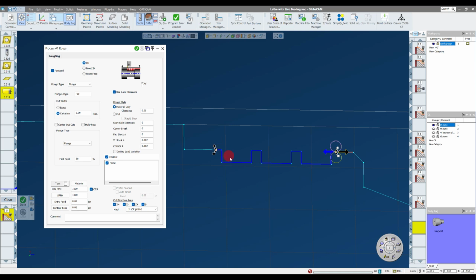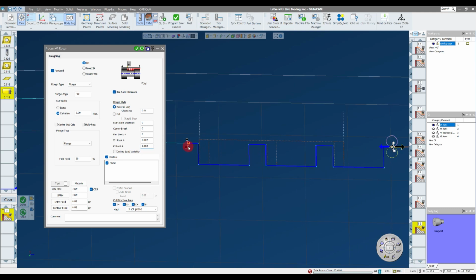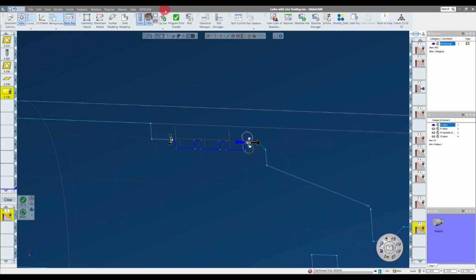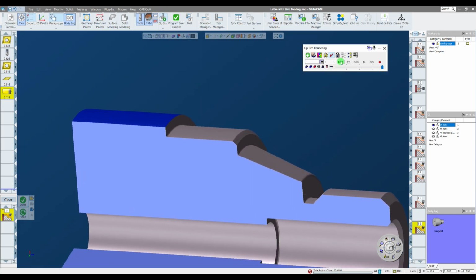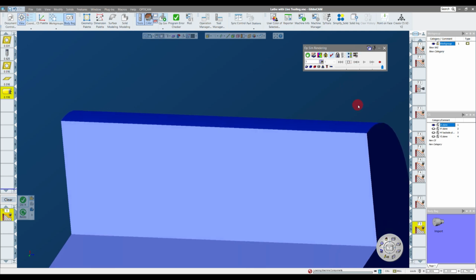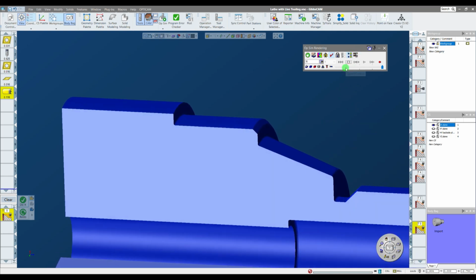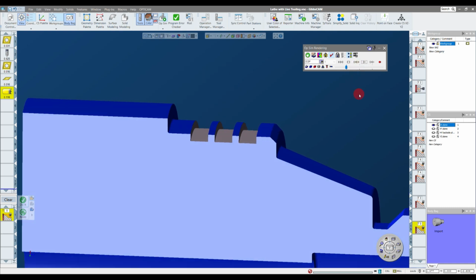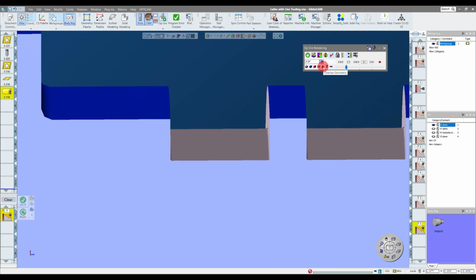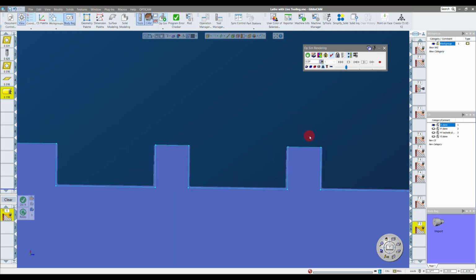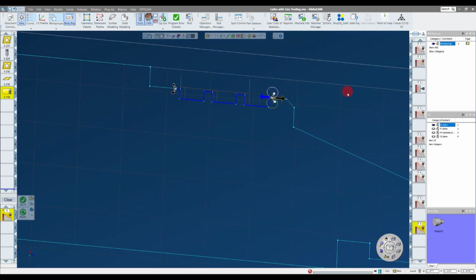I'm cutting, all the grooves are highlighted in blue, the tool's on this side. So if I click Do It, there are my roughing passes. It's one step over here and then one step over here. If I run my OpSim, rewind, use skip unselected ops, slow this down. There's my grooving tool coming in and doing 2 passes to rough that out. If I turn on my geometry overlay, I can see my 2 thousandths worth of stock on the bottom and all of the walls there. So there's my roughing pass.